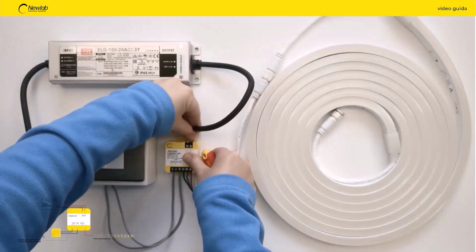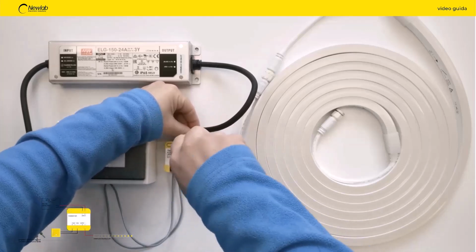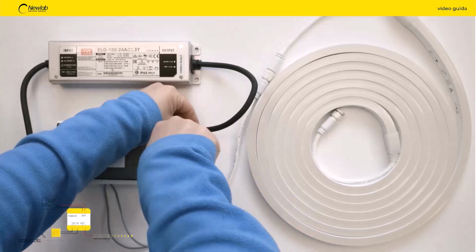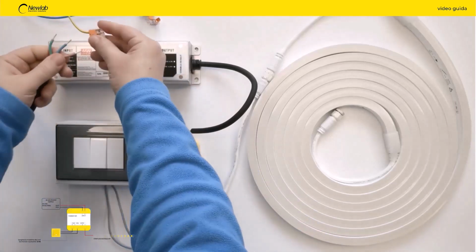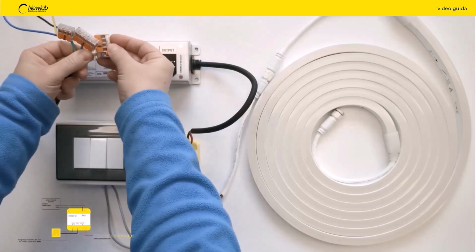Connect the output of the power supply to the input plus and input minus terminals. Connect the power supply to your electrical system and energize.